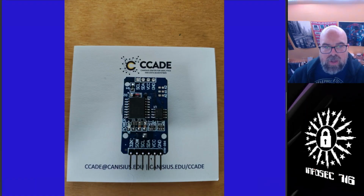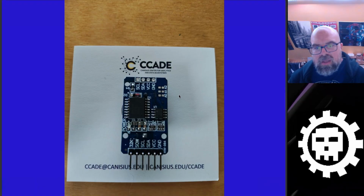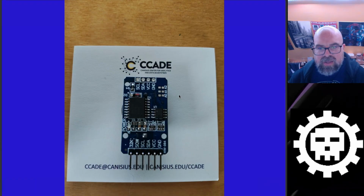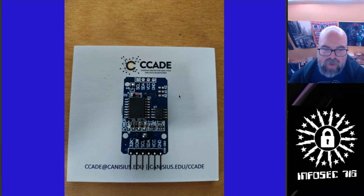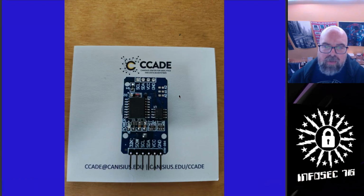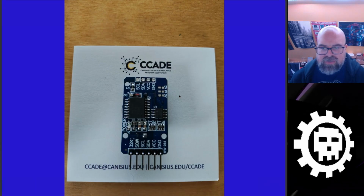Another thing that I want to point out, here we have these A0, A1, A2 solder pads. Those may look familiar. We saw something similar with the LCD backpack, the 1602 backpack in an earlier video. Those are for setting the address of the device on your I2C bus. By default, the RTC has an address of, I think, 0x58.